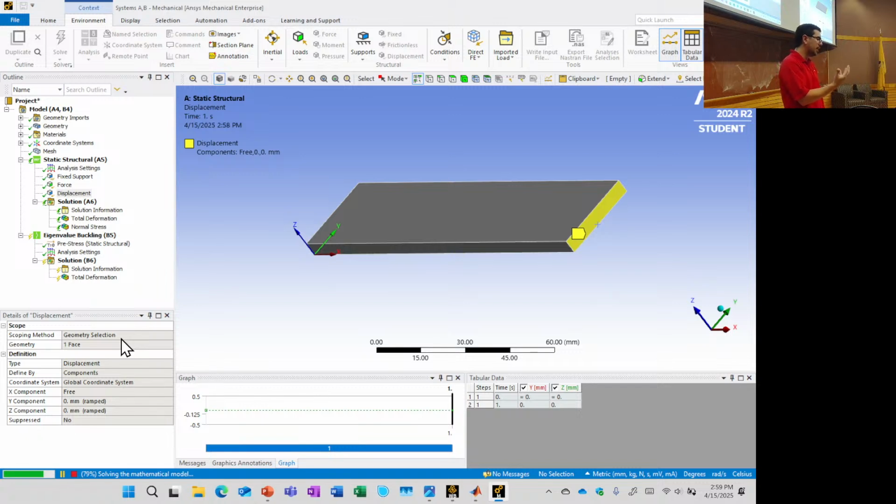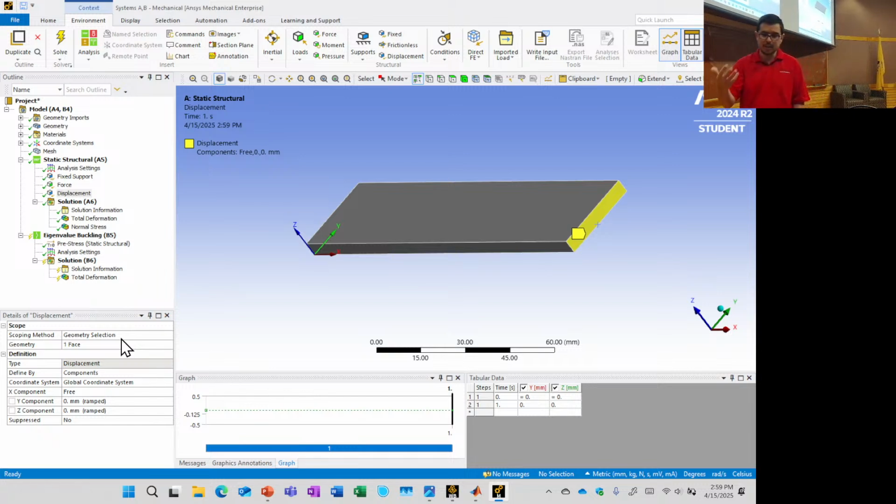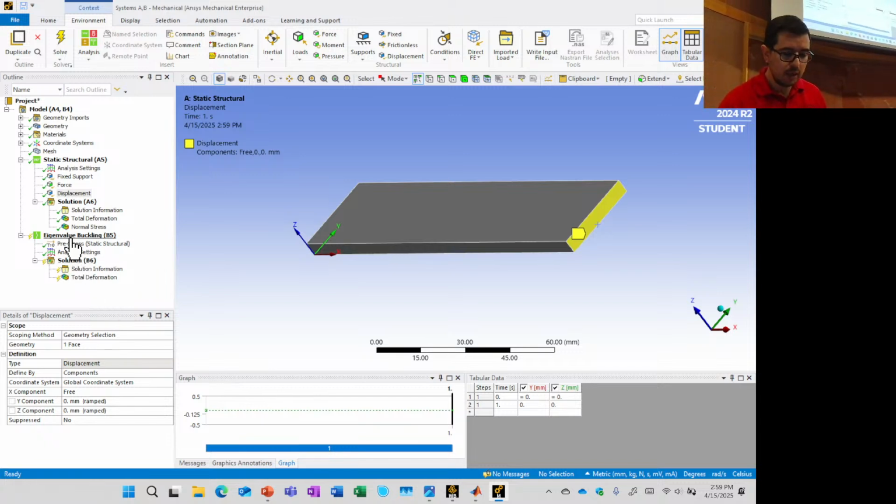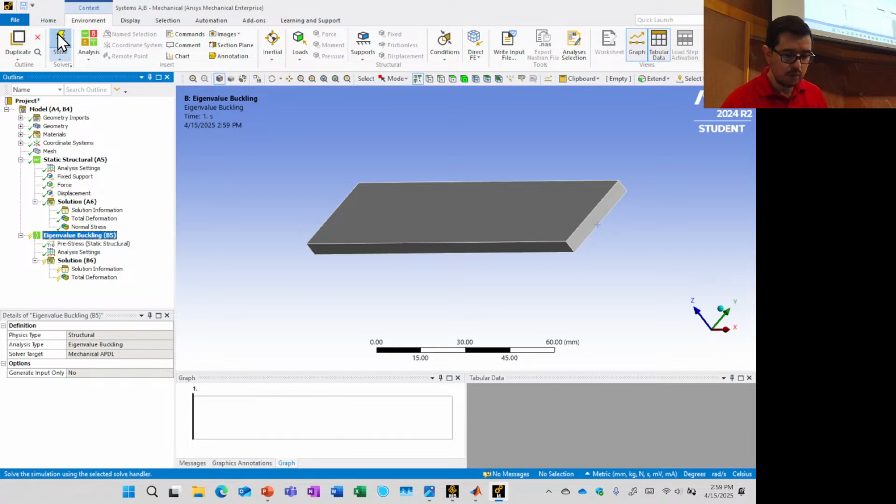What we should see is that instead of it buckling, the load multiplier for mode 1, instead of being less than 1, should now be more than 1. Because we're applying 10 kilonewtons, and we're hoping that our analysis is correct, it will be closer to 59. Oh, we had to run this too. Solve this.